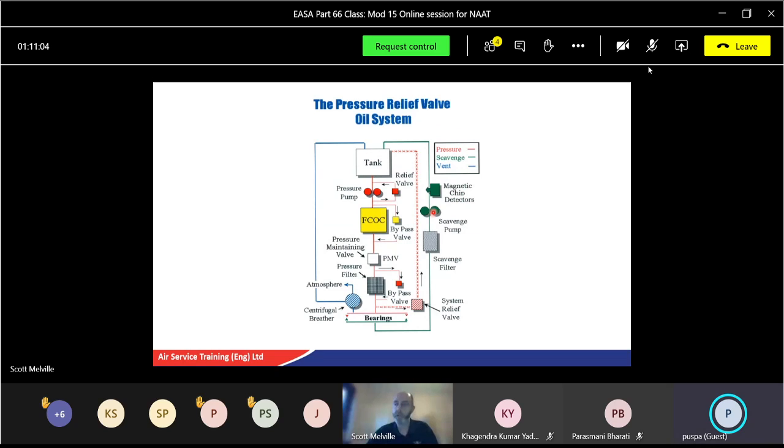I meant to take some photographs to show you inside the pump. They're all in line. The outputs are separated so they can't mix. But if you look inside the pump, you see small spur gears on one side and larger pump gears on the other side. So you can tell straight away which one is the high pressure one and which one is the low pressure. And the low pressure ones are bigger, which means it must be the scavenge pump. Scavenging helps return the oil back to tank, okay? Because of the larger volume, that's all it is.